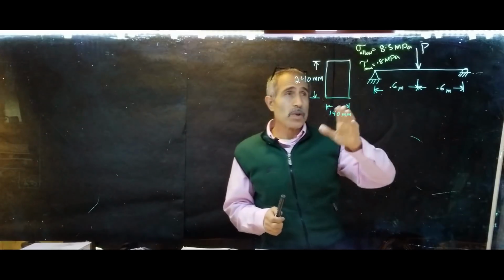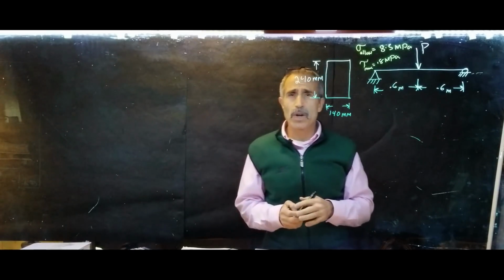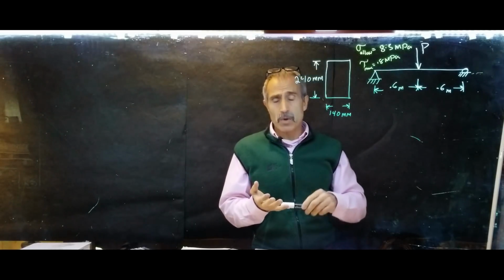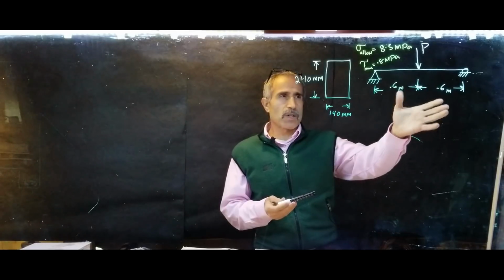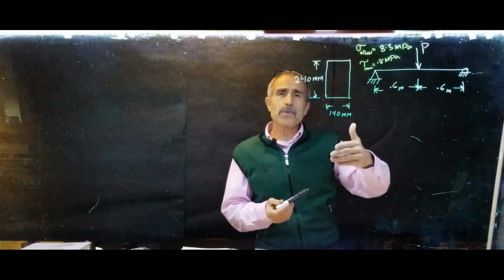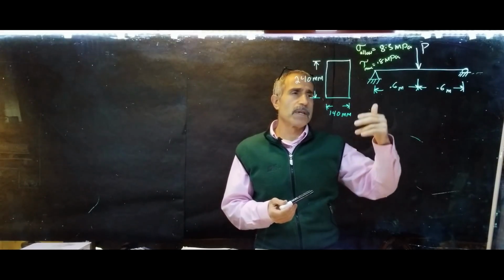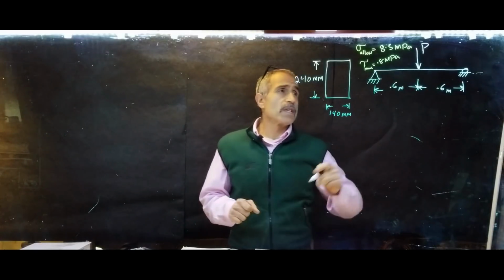One thing you want to do, let's start out with the shear moment diagram, because when you design a beam, you really want to know what is your maximum moment, what is your maximum shear. I mean, in here, we can just figure it out by calculations. Okay, my maximum, I can figure the reaction out, but it helps you to do a shear moment diagram. It will make it more defined. That's my recommendation.